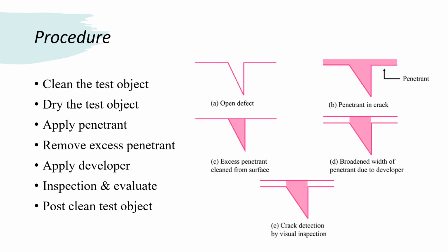After the cleaning, apply developer. After removing the excess penetrant, a thin coating of developer is applied. A thin coating of developer is applied over the surface to draw the penetrant out of the crack and increase its visibility.